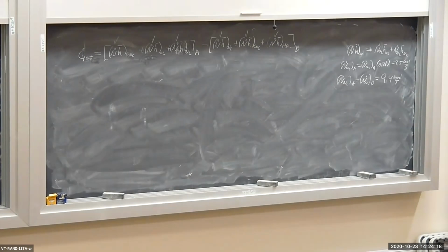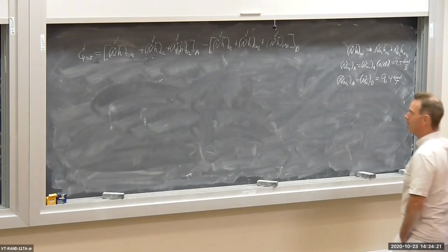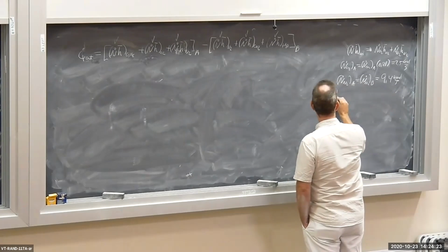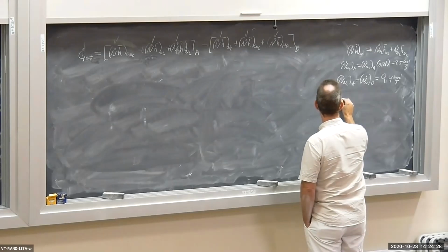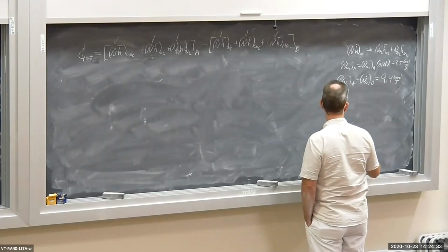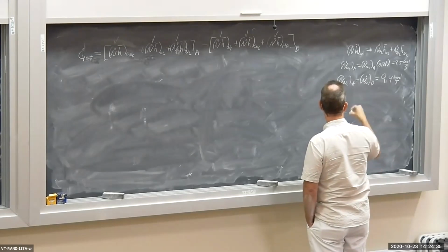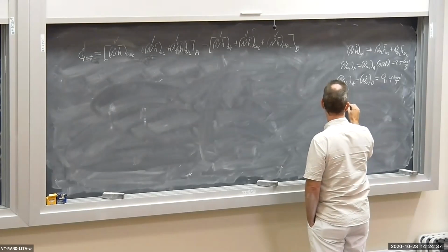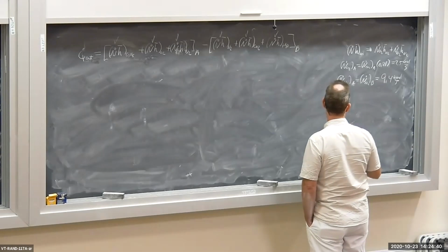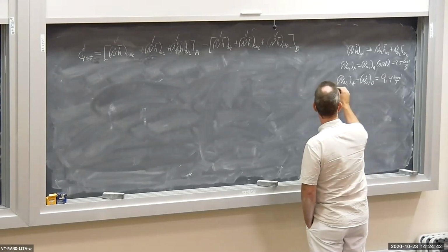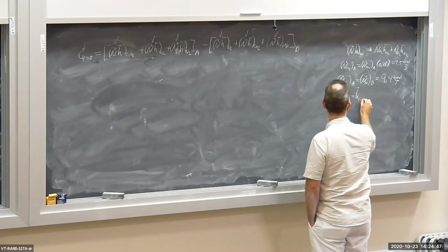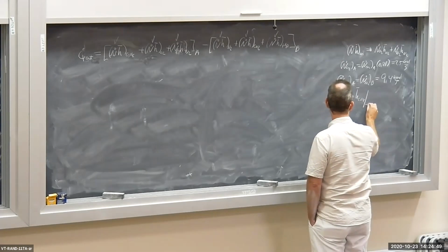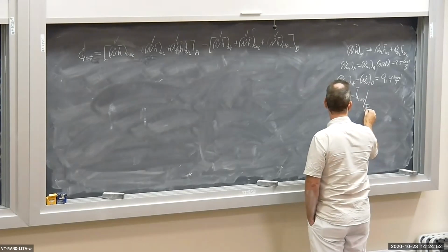Okay, so I got a lot of stuff here. Let's try to find some of these H's. Let's find the enthalpy H bar of the propane C3H8 evaluated at my inlet condition on the reactant side. So A, that's equal to H bar C3H8 evaluated at Tref and Pref.